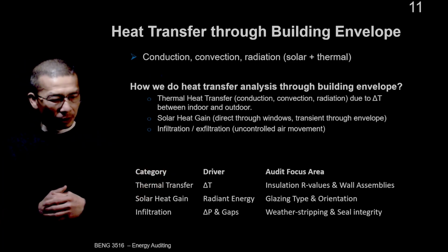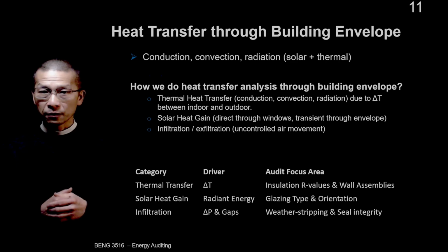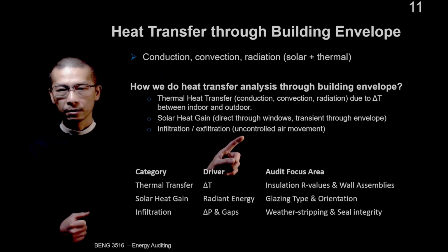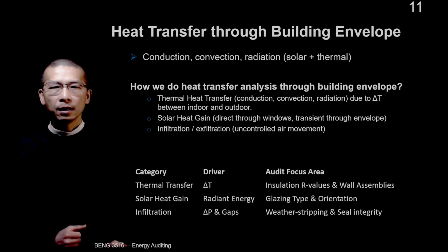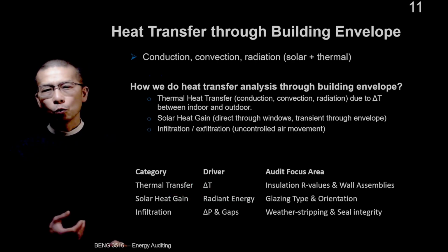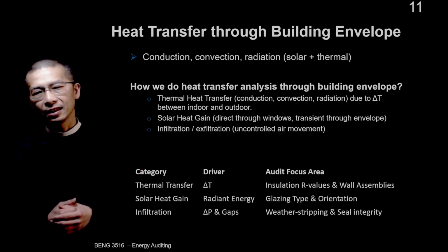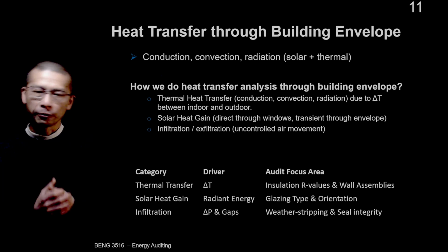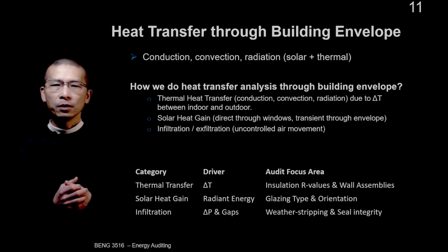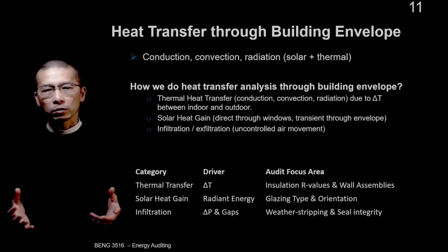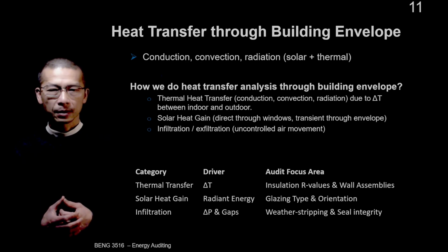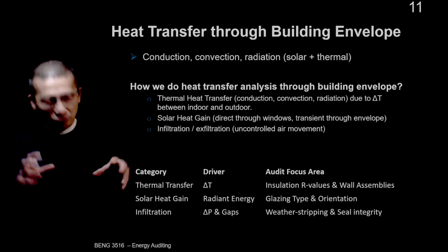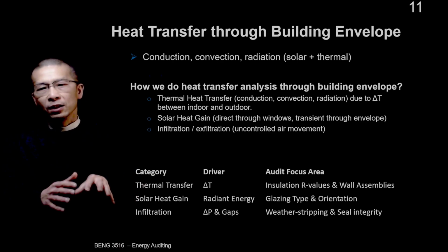And also infiltration and exfiltration. This is the uncontrolled air movement. As we saw with the infrared camera, this is not just about drafts, right? It's about conditioned air that we pay to heat or cool escaping through cracks, and unconditioned air forcing its way into the building.